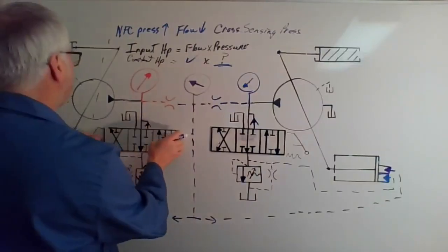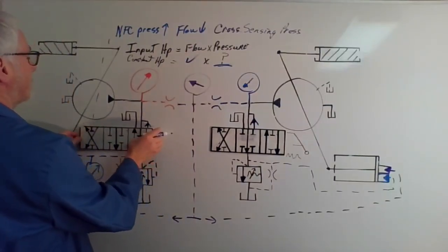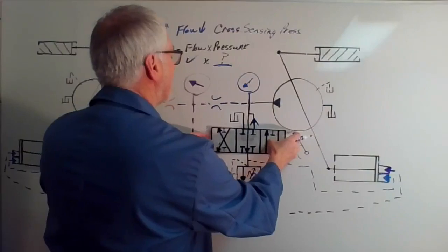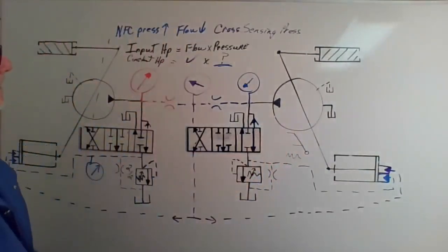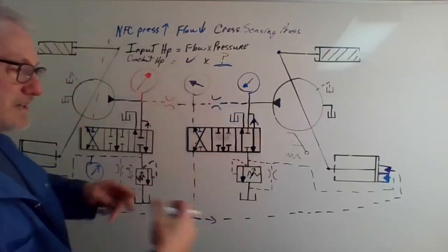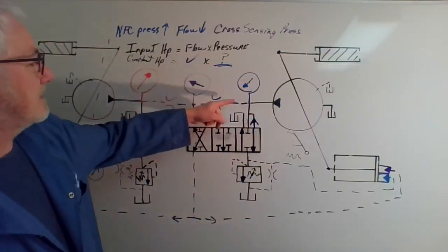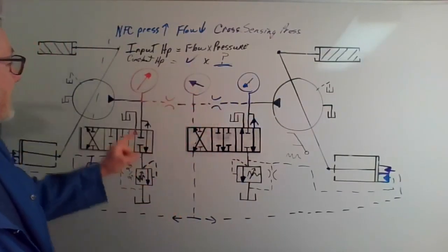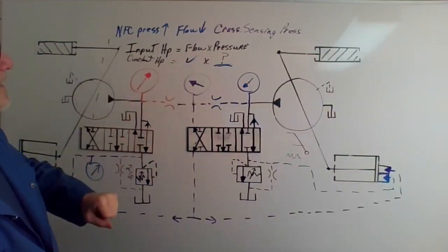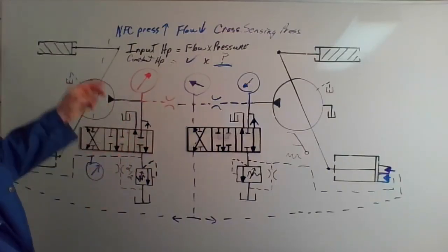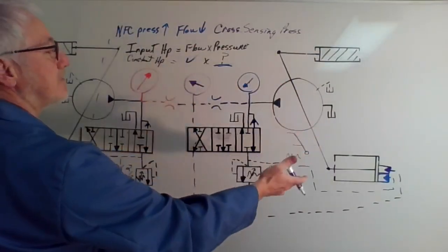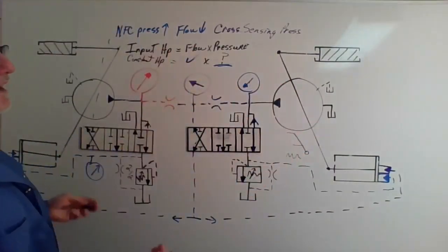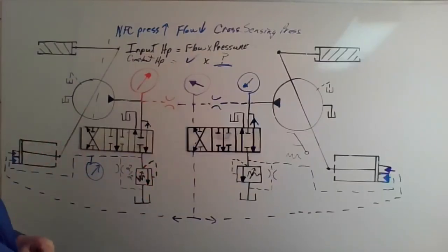So that when we're actually running stuff, and this one's kicking out, and this one's kicking out, when these are both going to town running multiple actuators, this one's loaded and that one's not. This is allowing me to hit a maximum swash plate angle for both pumps, so that this pump might pull 75 horsepower, this one's only going to pull 25 horsepower, and our engine horsepower might be a maximum of 110. That gives us 10 horsepower below stalling it out and overloading it.